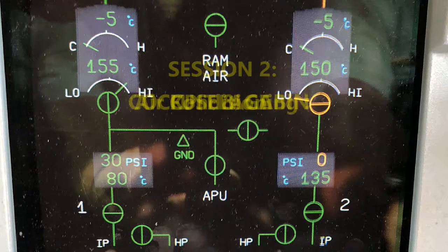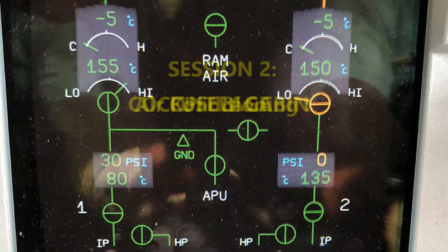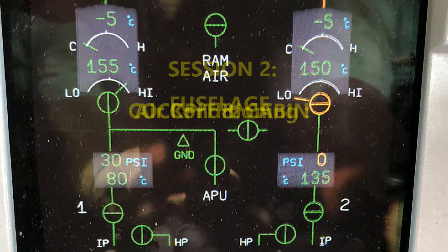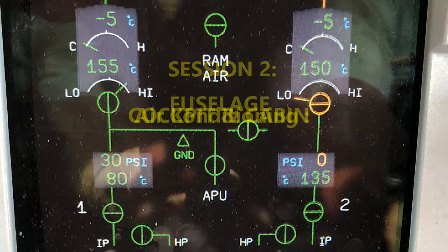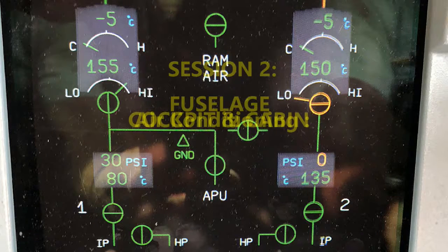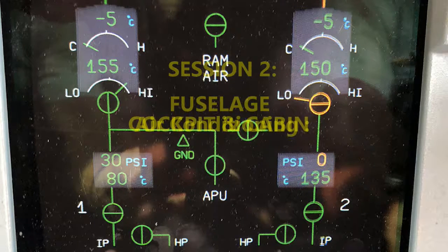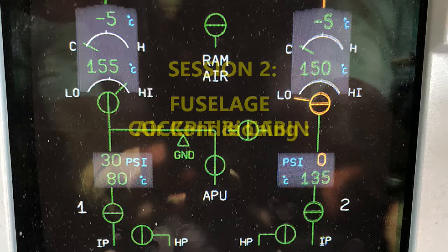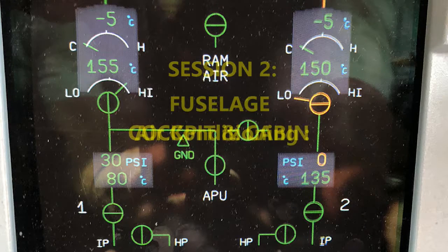Now, just a quick note on where it's located. This is in the aft end of the forward cargo compartment, near the mixing unit. We'll get into describing the mixing unit in a little bit. You've got a trim air valve, kind of basic there, and I'm going to go over what you probably already know. You've got your trim air check valve as well. Again, same panels that I mentioned earlier, you can access this.